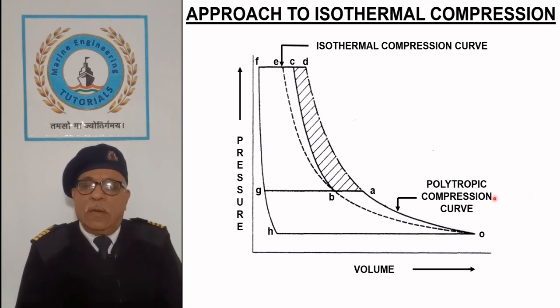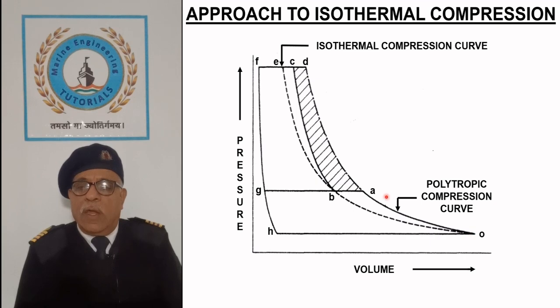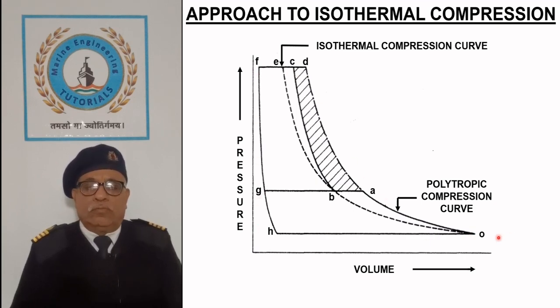On the other hand, if air is compressed polytropically in single stage, it follows the compression curve OAD, and the work done is represented by the area OADFGHO.